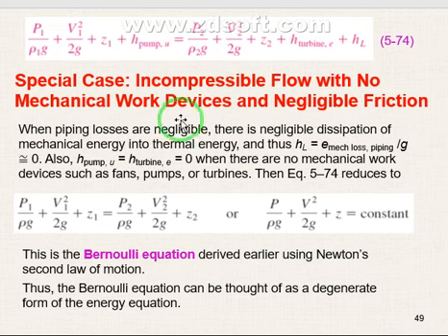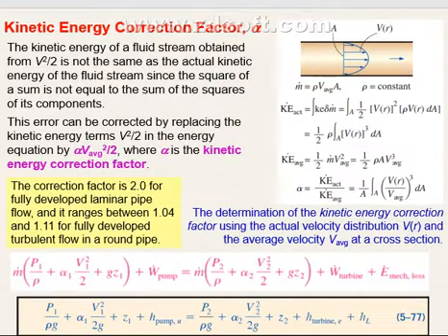General energy equation here again, different form, different figure. You will see that the Bernoulli equation is a special case of the general energy equation. You see guys, sometimes we have a factor if we go for an actual situation, because of the density and the flow profile, especially when we have unsteady flow, turbulent flow, whatever, the velocity profile will affect the behavior of the equation.